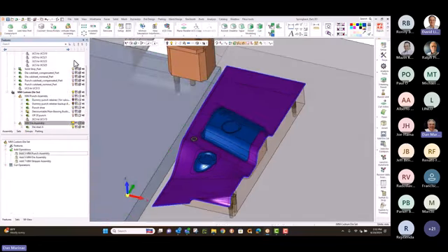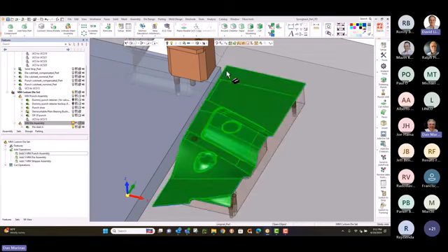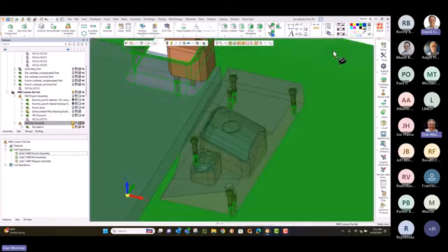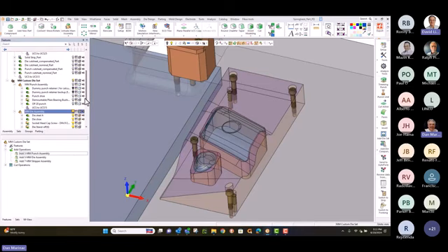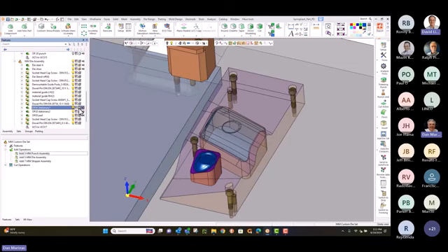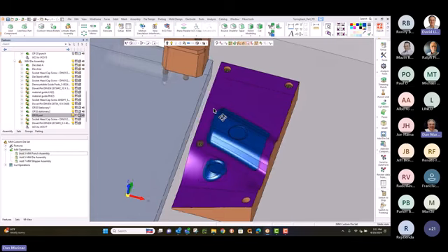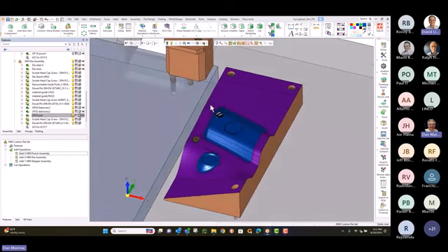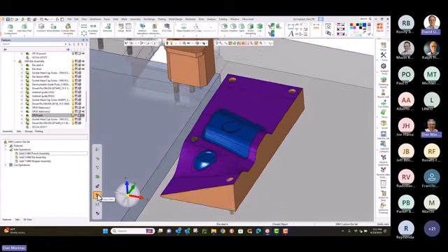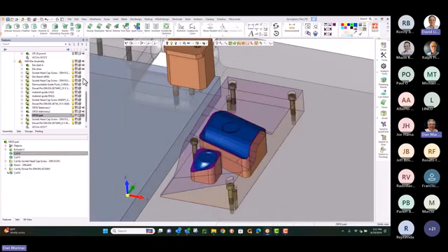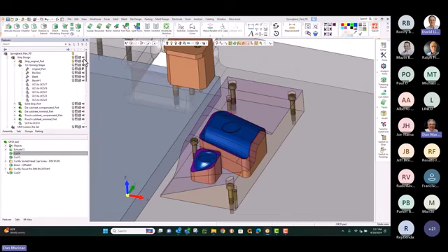Now with that, we talk about changes that might occur. Here we did it at 100%, which would be aggressive for the first time and looking at it. Again, in reality, we would take what we did with those cut sheets and we would take it back into our simulation and compare that and do that again and again. It might have a bit of an iteration doing it several times, but it's important that we find out here rather than find out when we cut the steel. It saves us a lot of time and money. That's the whole purpose behind it, of course. So we can do that.